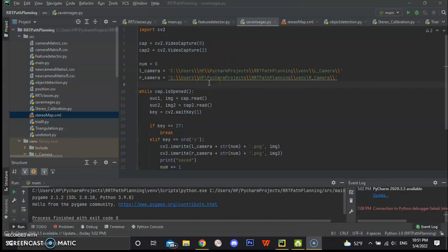For this, I first created a stereo camera setup, which consisted of my webcam and my mobile device. Both devices were placed approximately 28 centimeters away from each other. I tried to mimic a stereo cam, but the problem was that the focal length of both my camera modules is different, so whatever I do, I won't get the right parameters. So this is just a prototype of what is possible with a stereo camera.